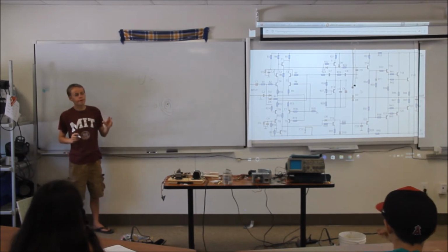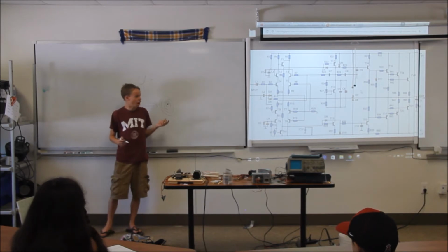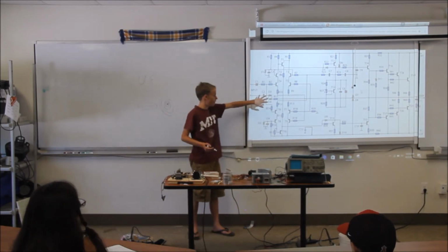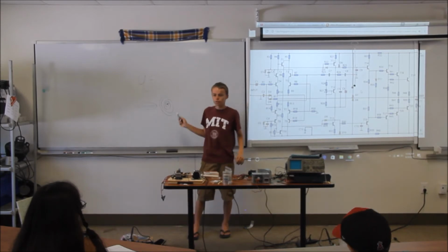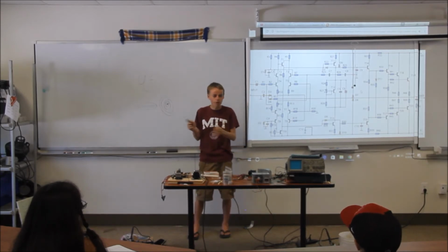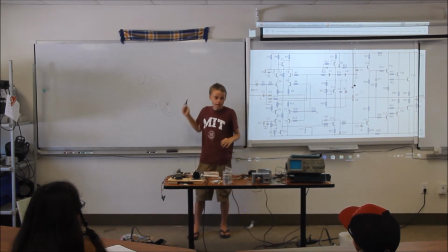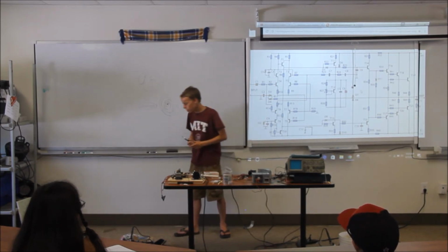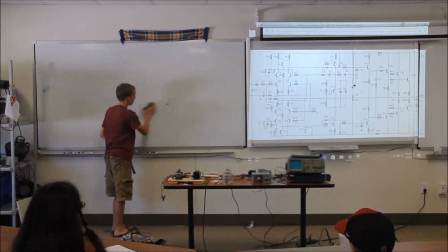And these small capacitors can be used for transmitting audio, like in this amplifier, to block out DC voltages, which will make your audio sound all weird. They put capacitors so it blocks the DC like I was saying, but it lets the AC pass. It's pretty cool. So now, back to my power supply that I was talking about before.